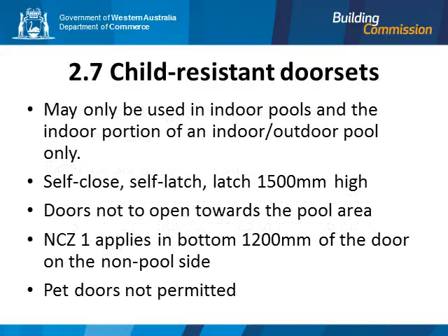Clause 2.7 covers child-resistant door sets. The 1993 standard did not detail where doors could or could not be used. This was addressed in the regulations. Also, the standard was silent on the direction of opening when it came to doors, with the general application being that doors could swing or slide in any direction. Under the new standard,